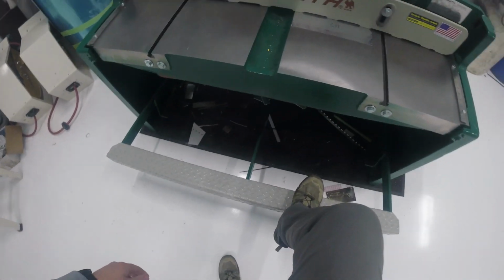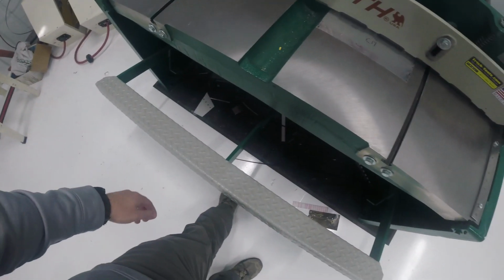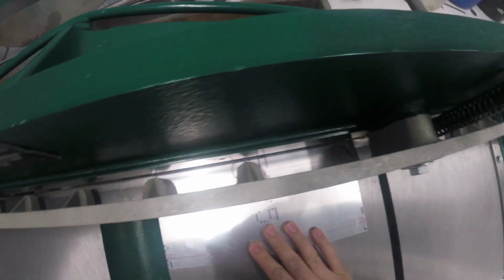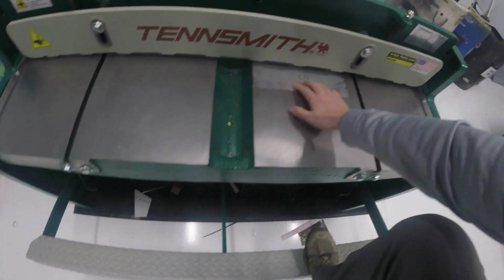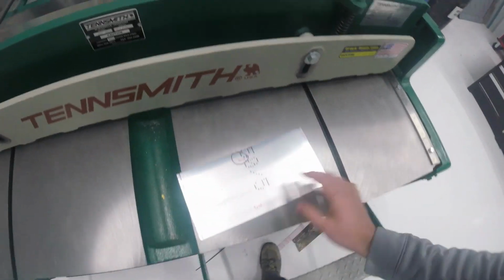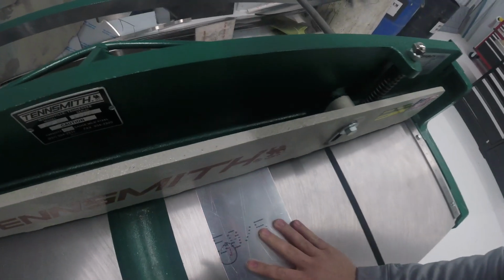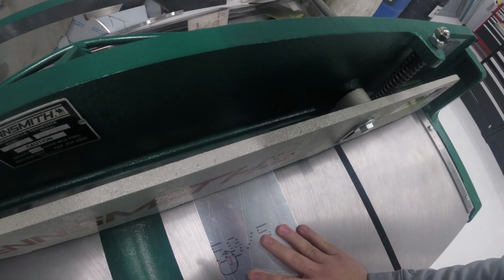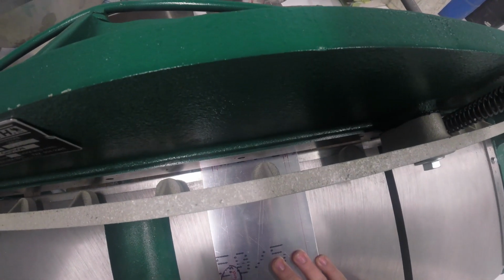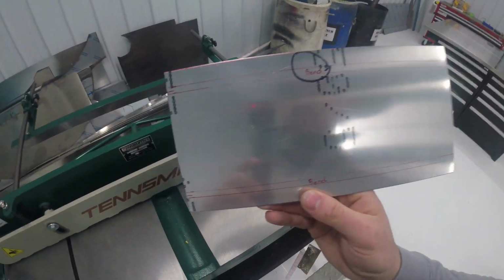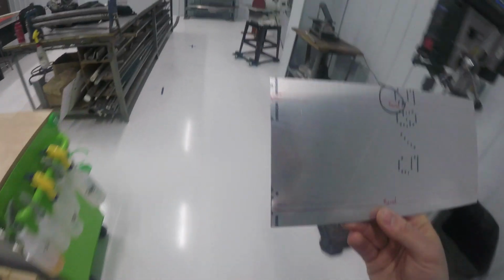And next thing you want to watch for is when you push this down, don't leave your other foot up under there, because you will smash it. So just be careful. Again, we're going to make sure our lines are lined up, then we're just going to give it a good stomp. And just like that, we got a nice cut. We'll go ahead and cut our last end over. Line it up. Give it a good stomp. Just like that. Now all we got to go do is put it in the brake and bend these two pieces up.